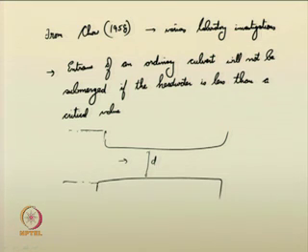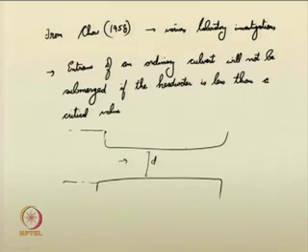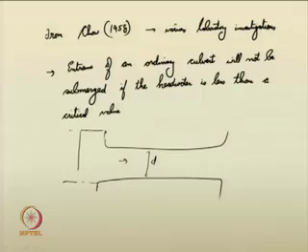This raising of the headwater above the top portion of the culvert does not guarantee that the flow inside the barrel will be full. It does not guarantee that. It requires another mandatory condition: the height of water must be above a certain critical value.